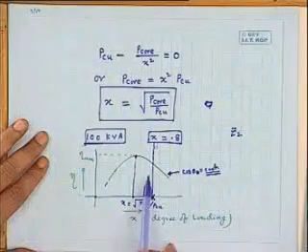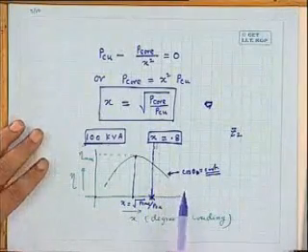Now the question is, where do I like to have this maximum efficiency, x? For example, as I told you, if you consider a 100 kVA transformer, and the transformer is so designed that the value of x is 0.8, then what you see is this: the maximum efficiency will occur not at the full load condition of 100 kVA, but at 80 kVA. The moment you want to operate the transformer at its rated kVA, its efficiency will go down definitely, because it will fall this way.